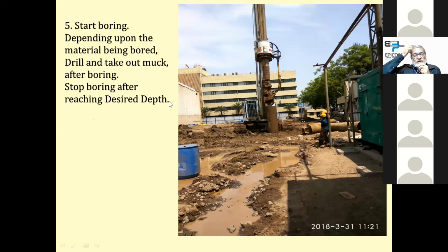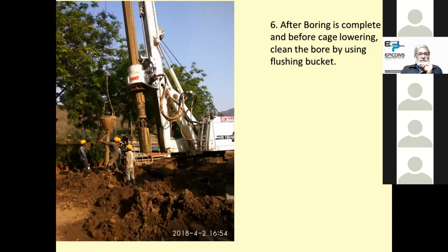Normally, you get guidelines from the geotechnical report, but you can also check the penetration for 10 minutes. When it reaches normally 5 centimeter or less, you stop, but broadly you go by the termination criteria, which Mr. Vaishampayan will be talking about.